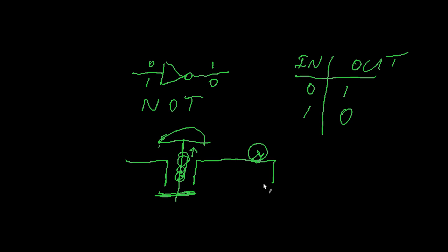So what happens here is that when there's no pressure against the push button, this spring is pushing it up, and it's pushing the bar against these contacts, and it's in a closed position so that current can flow through the wire, applying the voltage to the light, turning it on.